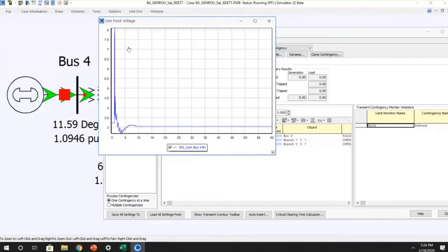So the gist on the machine is somebody set the parameters that define the response of that exciter, and they set them for a reason. You're balancing when you do a control system. We'll talk about control system design in a little bit, but you're looking at how fast you respond, how much overshoot is allowable, how much steady state error you have, things like that. That all goes into control system design, which is ultimately what we're doing on these generators here.